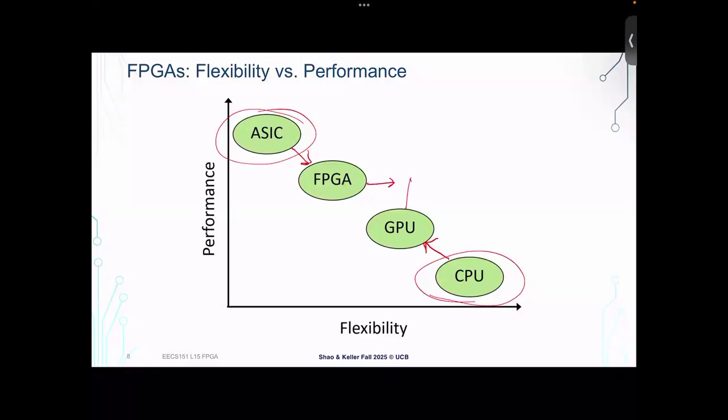I think the big difference between FPGA and GPU in terms of flexibility is that if you want to do two different things on a GPU, it's just a matter of launching a different software binary, which you can do in seconds or milliseconds. Whereas if you want to have different functionality running on the FPGA, you have to flash a new bitstream on there, which is slow and takes specialized hardware.